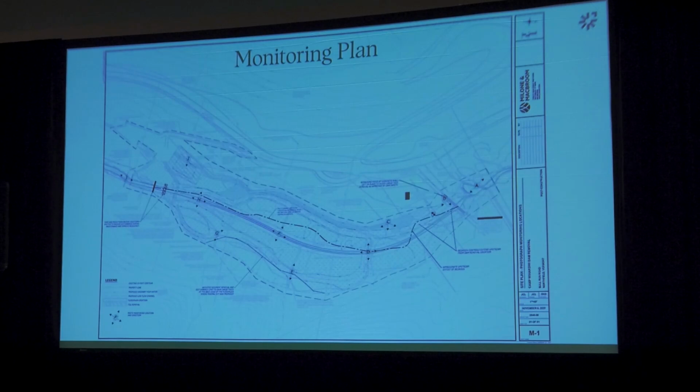We'll take photos in each direction and record a GPS point of that location so that during the project, after the project, and in the following years, we can repeat those same pictures and have good comparisons of before, after, and going forward. So it's good to make sure you do this before any construction starts and changes the existing conditions.